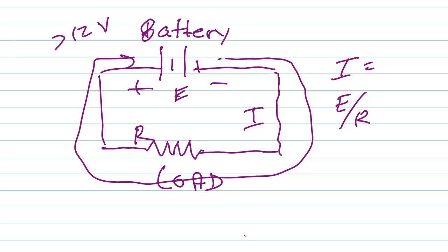You generally will either ground the negative or the positive terminal of the battery. Let's just suppose that we ground the negative side. Now, when I say ground, that can be an actual connection to the earth, like a ground rod pounded into the earth, or in the case of a vehicle, a boat, an aircraft or something, the large massive metal that makes up the chassis or frame of that vehicle. And here in the United States, that's almost always the negative terminal of the battery and the electrical system.